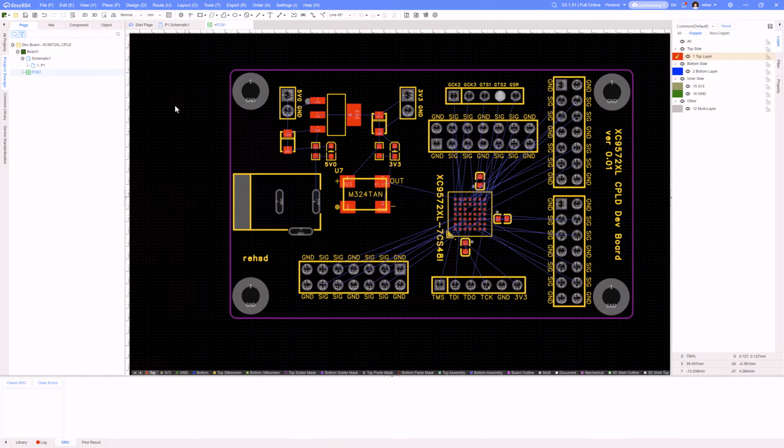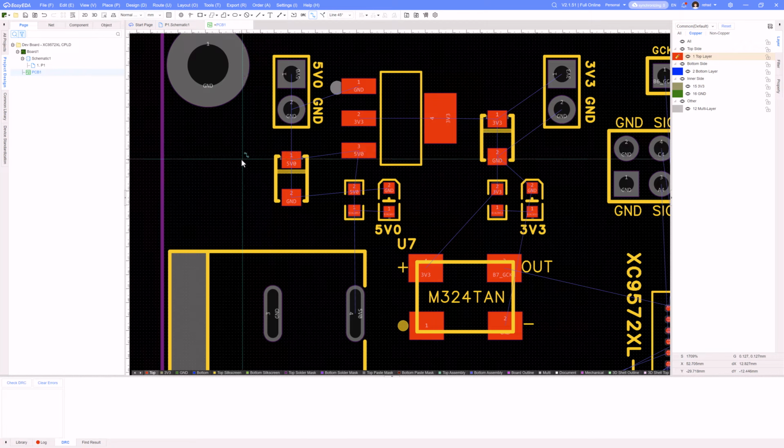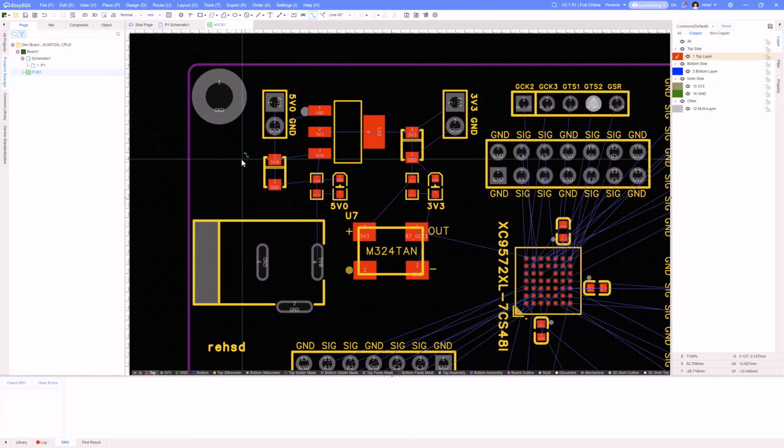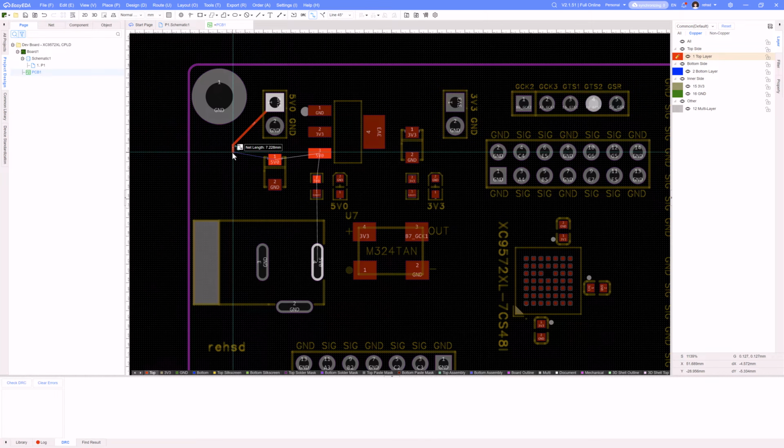Now what I do is just simply hit Alt-W, that's to draw a wire. And then when I come over here, I can click on where do I want to start drawing from. For example, I want to go from this 5 volt down to here, so I can just click on it. And it's red, which if I look over to the far right under layer, red is top layer. Now if I want to go to the bottom layer instead with this, I hit Alt-B, that's bottom layer. Or if I had other layers I wanted to go to, like a 1, 2, 3, 4, 5, I just hit those numbers. Now in my case, I've just got a top or a bottom, so it's going to be Alt top, Alt bottom that I can run this on.